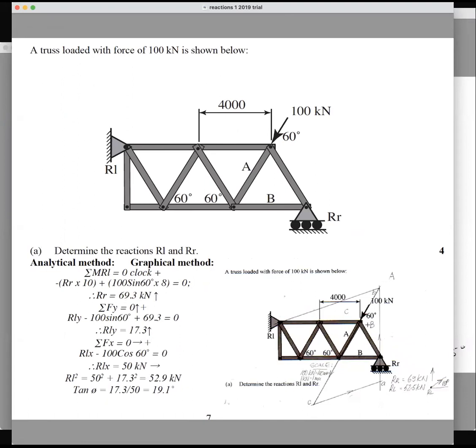So you know that you've got your force going down there, you've got a force going through there, and you know that you've got to have a force at 90 degrees to that surface there. So you know the direction of that force is vertical. We don't know whether it's going up or down yet, but you can just see that it'll be going down because it's got to oppose that motion there.